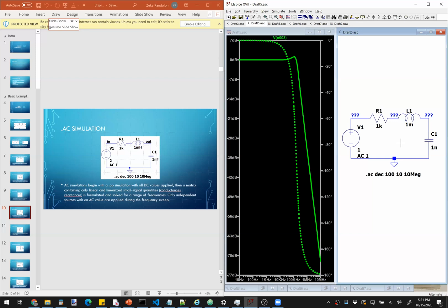And this is basically the same thing as what you've done anytime that you've analyzed a circuit, say in your microelectronics class, when you analyze what is the gain of this amplifier. Gain in and of itself is a linear concept. It is meaningless when it comes to the second or the third harmonic, or higher orders of the Taylor series expansion, right? When you specify what the gain of a circuit is, you're only looking at the first 2 items in the Taylor series expansion. The DC is the first element, and then the first derivative is the second element.